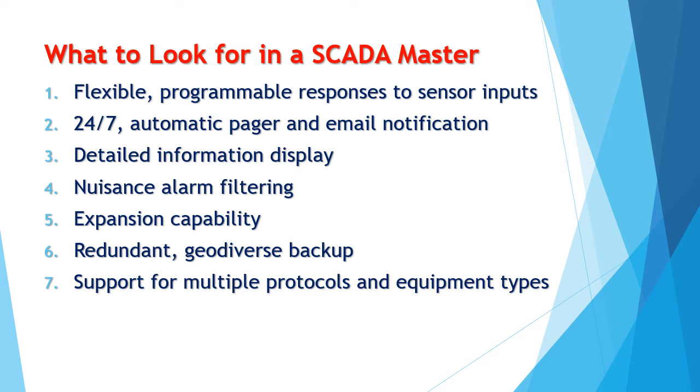We've seen what you need to look for in a SCADA RTU. Now let's see what you need to look for in a SCADA Master. First is flexible and programmable responses to sensor inputs. So you should look for a system that provides easy tools for programming soft alarms and soft controls.